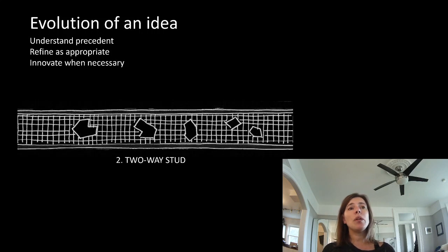So then we said, well, you could build in a little more tolerance with a 2-way stud system. And you have a series of studs this way and a series of studs this way. If they're each 200 or 225 millimeters in depth, well, you're now out approximately to your window spot, and now maybe you can just frame around your windows.